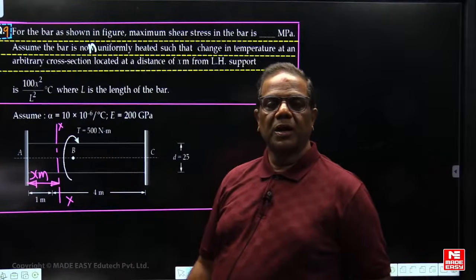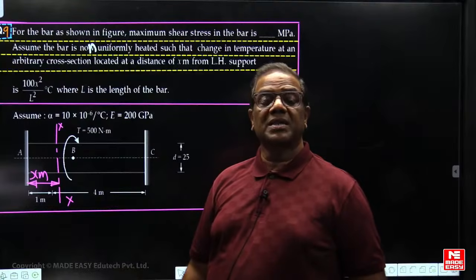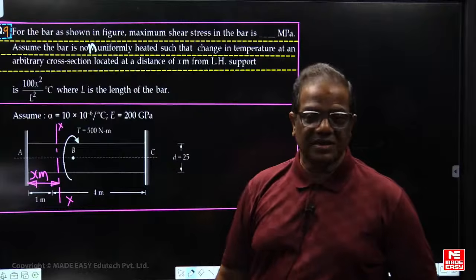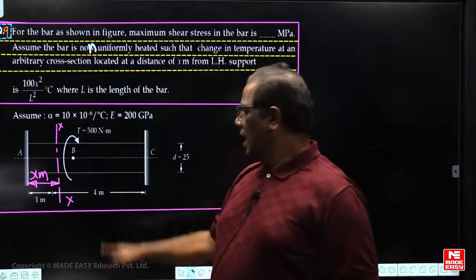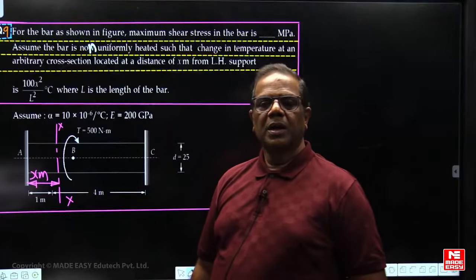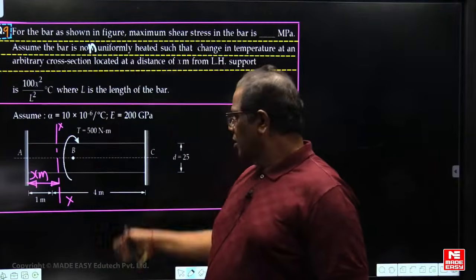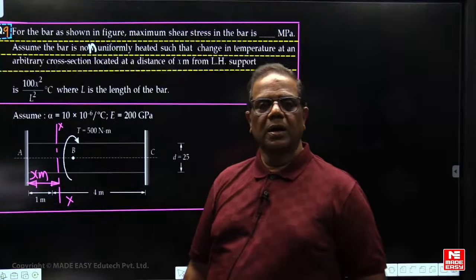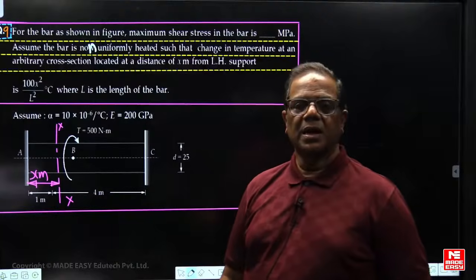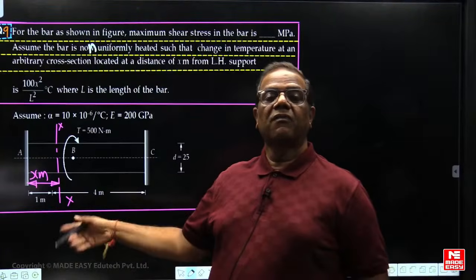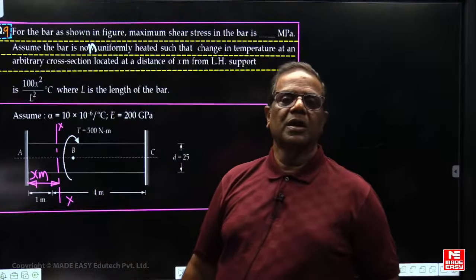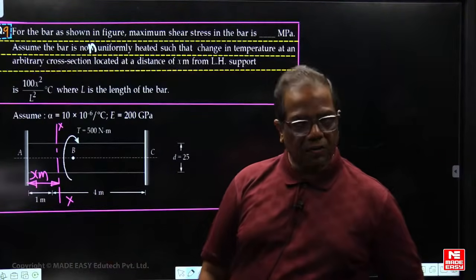कितना स्ट्रेसेस मिलेगा? ड्यू टू चेंज इन टेम्परेचर से आपको थर्मल स्ट्रेस मिलेगा. The thermal stress will become an axial stress, compressive, and due to the twisting couple आपको टॉर्शनल shear stress मिलेगा. Then you are getting a combined state of stress. So on the cross section you are getting one normal compressive stress due to change in temperature, and one torsional shear stress. So on the cross section you get combined stress. Then the principal stress concept is required now.